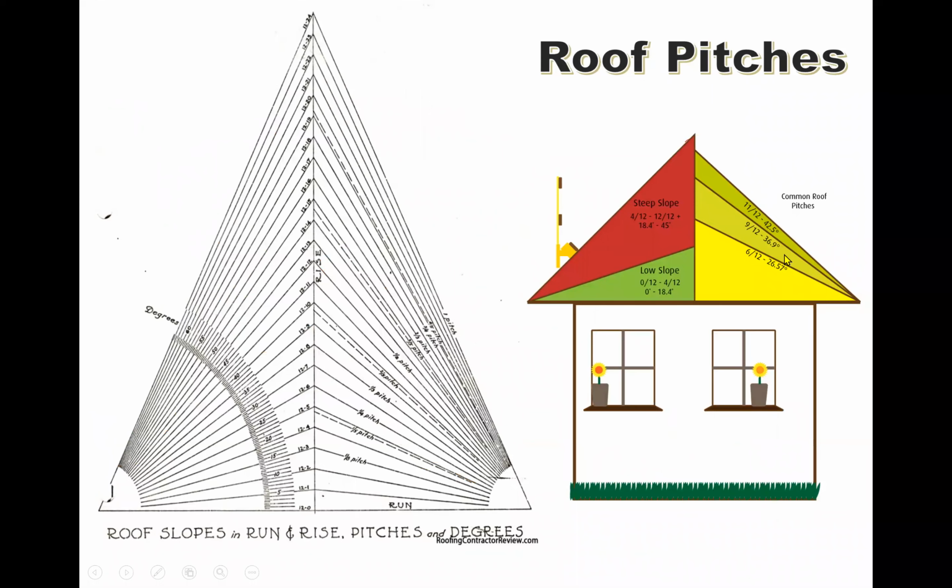So this is showing the pitches, right? This is about where the 16-12 will be. You have a 9 in 12 and 11 in 12 and different pitches shown here. But let's choose one of them. Let's choose a quarter pitch, which is up to here. So what it means is that the height of the roof will be from here to about there.